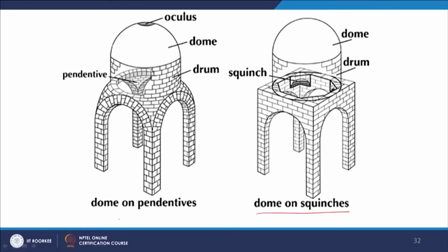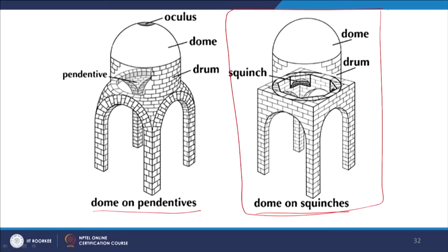and the interior architecture. If we talk about construction and structure, there is also a system in place for how one constructs a particular element. So if we are talking about the space making element, the dome, this is how it is constructed on squinches, and when we don't have squinches, this is how it is constructed using pendentives. So again there are systems in place which we have the references to follow and understand.